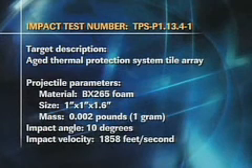I'm going to show you some impacts on tile first. Then we'll move into some impacts on RCC with various debris types. The first set of impacts I want to show you, the target is an aged thermal protection system tile array. It'll be impacted by a 1 by 1 by 1.6 piece of foam.